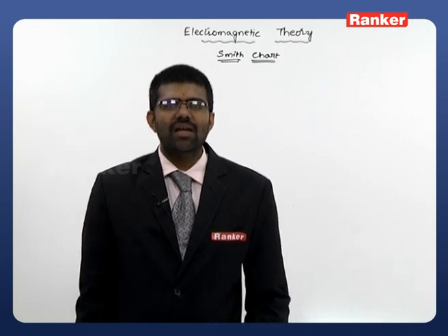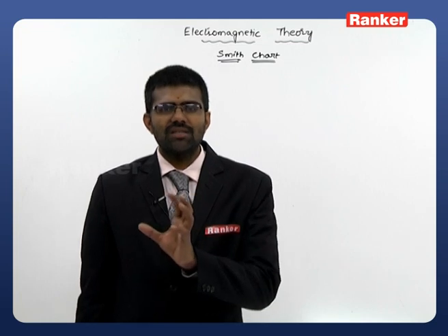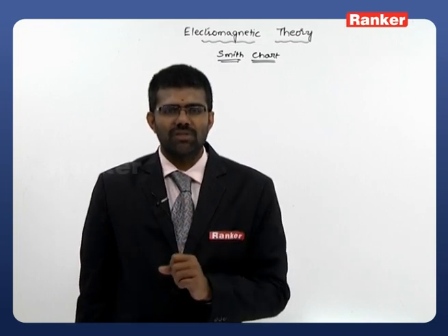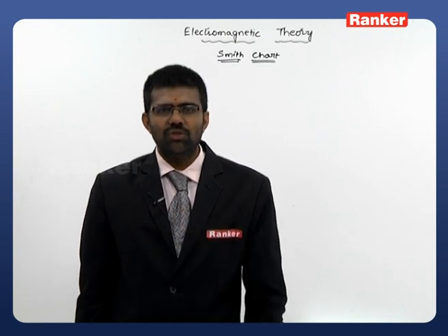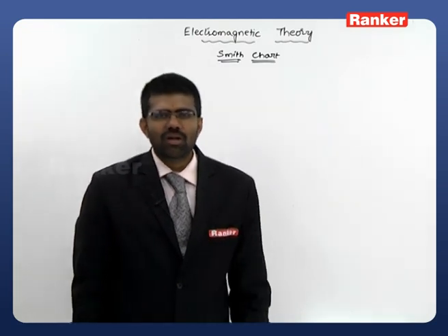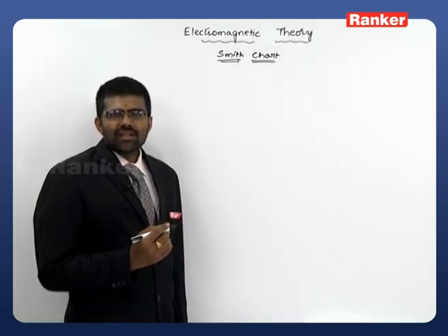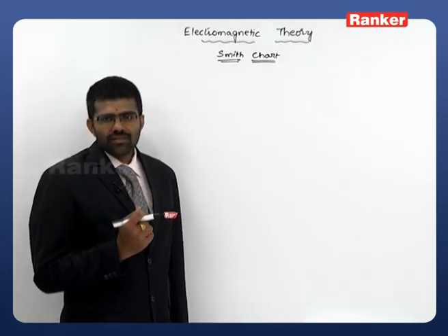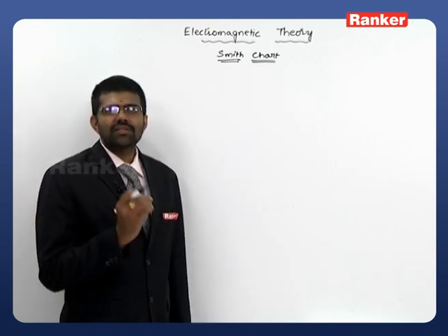In this session I will start with how to develop the Smith chart, and later I will explain how to understand it, what the properties of the Smith chart are, and then we will solve very simple problems based on it. So what is the basic property of our Smith chart and how was it developed? Smith considered our voltage reflection coefficient parameter, and he manipulated that reflection coefficient slightly.